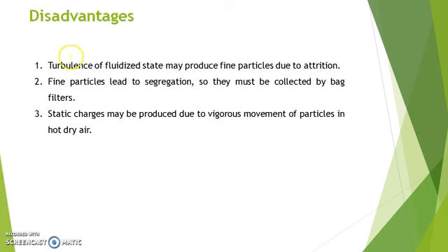And similarly, disadvantages: turbulence of the fluidized state may produce fine particles due to attrition. Fine particles lead to segregation, so they may be collected by the bag filters. Static charges may be produced due to vigorous movement of particles in the hot, dry air.